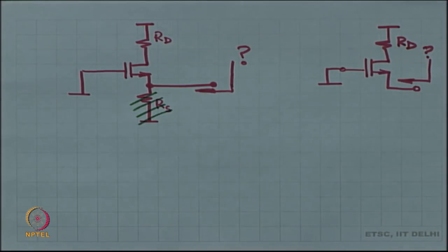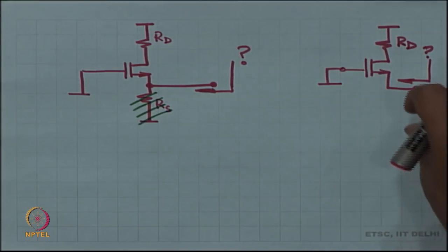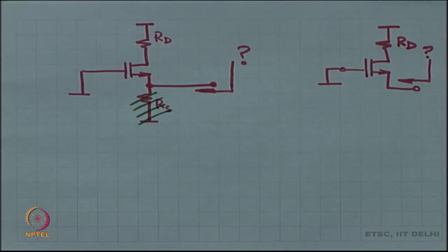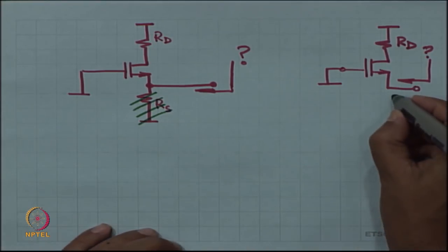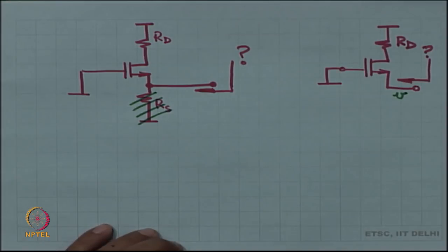How will you do such an analysis? You are going to apply a voltage source and see what is the current going into the circuit. Now, unfortunately, this is an impedance calculation, so no other method is going to work out. So, we are going to apply a voltage over here, let us say V, and then we need to measure what is the current that goes inside.